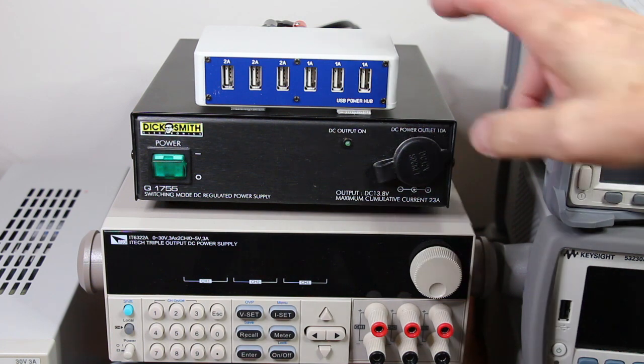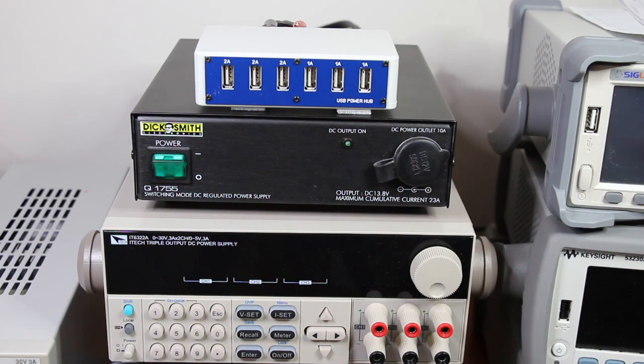And here is my power supply cluster in its place on my workbench. It's important to point out that this device has overcurrent protection, short circuit protection, over temperature protection, and over voltage protection. And its switching frequency is 1.1 megahertz, making easier the task of keeping a decent ripple at the output.